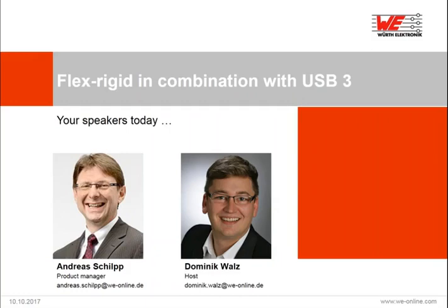Regarding the temperature resistance, polyimide is much better compared to a rigid material. So if we are talking about rigid materials with a Tg of 150 or maybe 170 degrees C, polyimide has a Tg of much more than 300 degrees C. So in the complete system, the flex material never is the weak point. It's always the rigid material. So don't argue, there's no problem with the flex material.